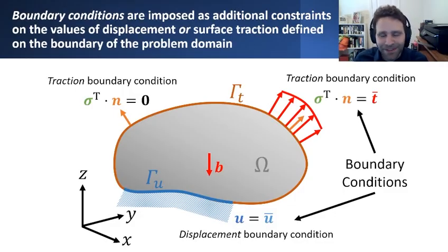The simplest one you can think of is just insisting that the displacement at this constrained boundary, let's say that hatched region in blue, is fixed or constrained, such that it's just purely equal to zero. But it could be prescribed to be some non-zero value in general, which I'm denoting here with a u with an overbar, just to say that maybe I'm prescribing this u with an overbar over that particular portion of the domain, or on the boundary in particular.